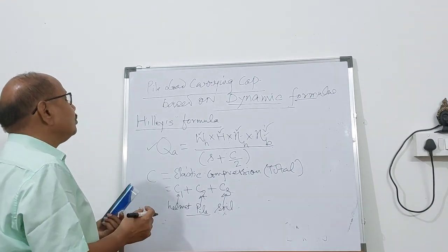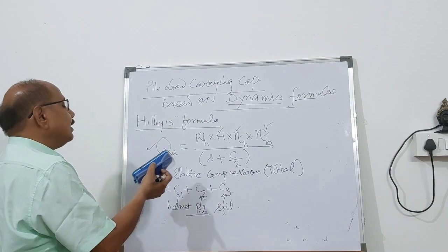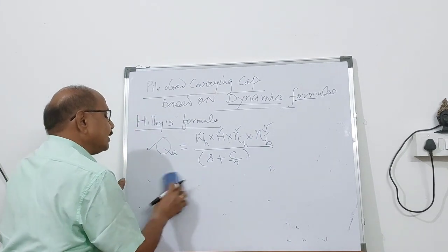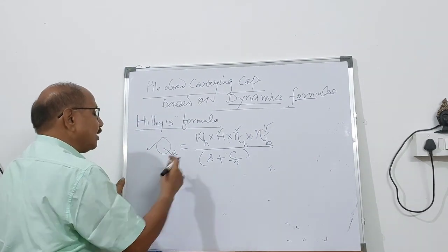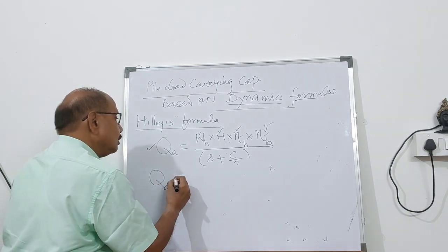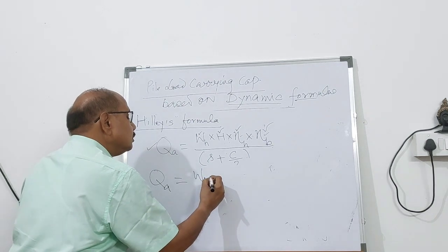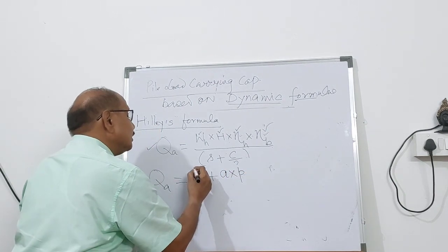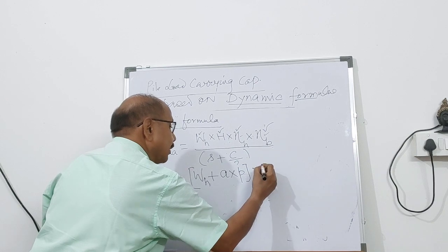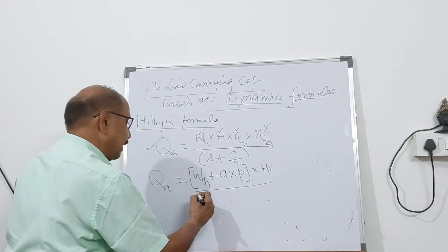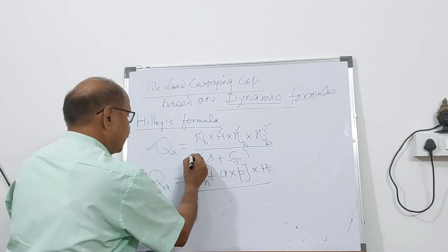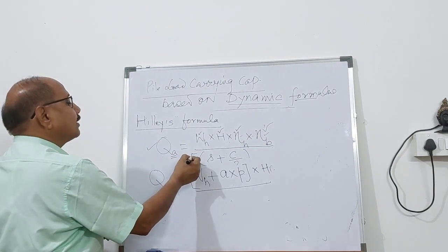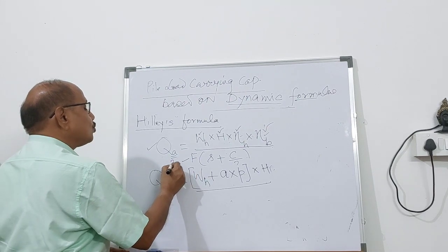And suppose you are going to have a single acting or double acting steam hammer. So for a steam hammer, what you can do is that the allowable load will be WH plus the area of the piston into the steam pressure. You add up, multiplied by H, divided by, here you will have to give the factor of safety also, because it is allowable load. So you will have to give the factor of safety in this equation. This factor of safety is 2.5.